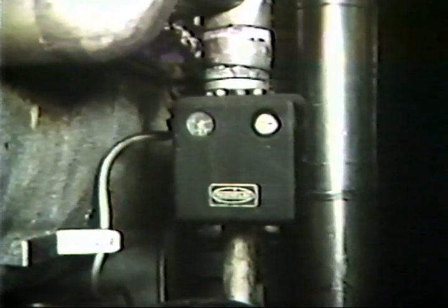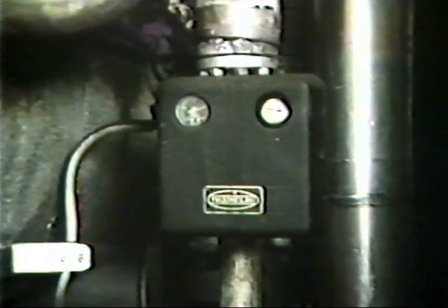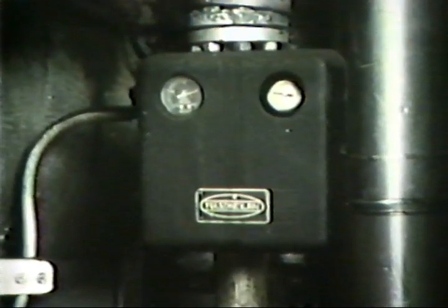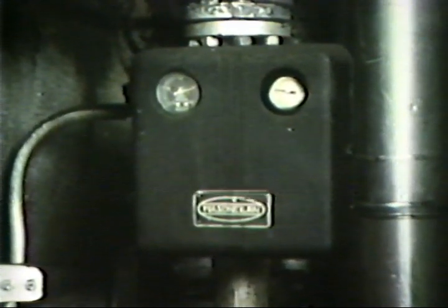In a pneumatic control system, it's the responsibility of one instrument to ensure that the system takes corrective action to keep a process variable at set point. This instrument is called a controller. A pneumatic controller is an instrument designed to produce a corrective signal that enables a control system to maintain a process variable at set point. In effect, the controller is the control center of any control system because it determines the system's corrective action.